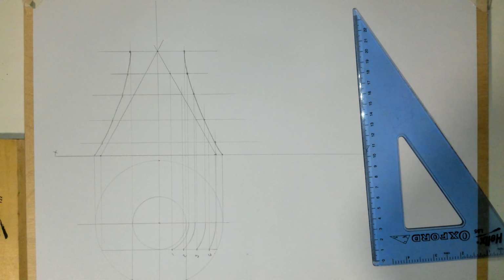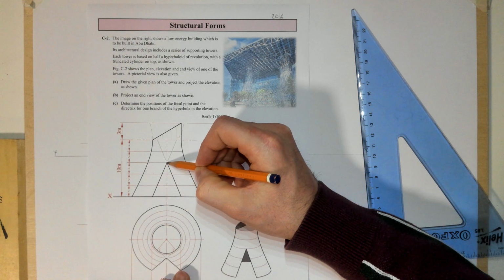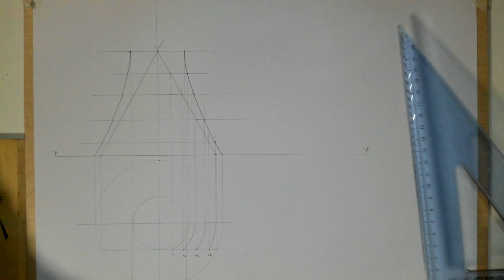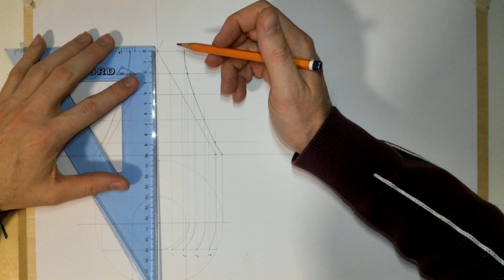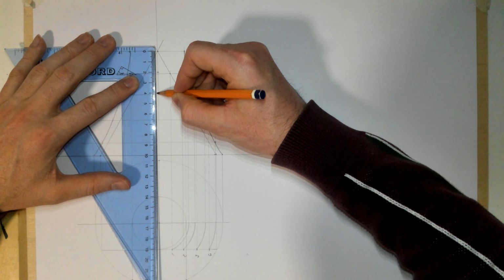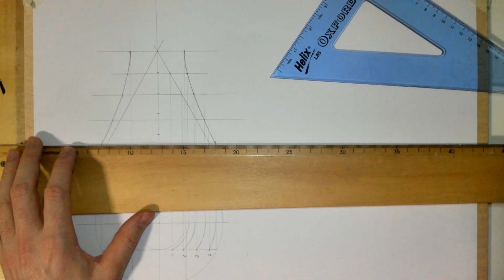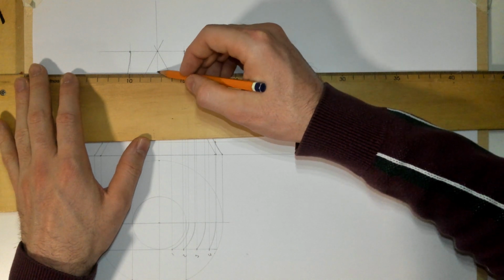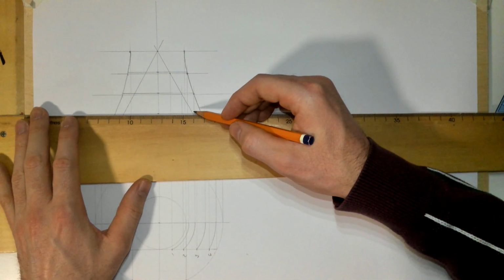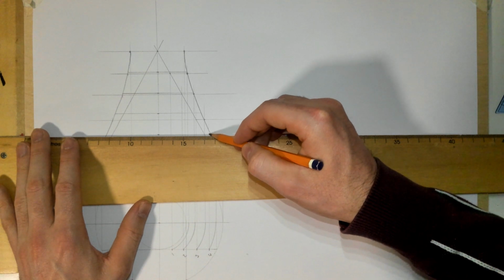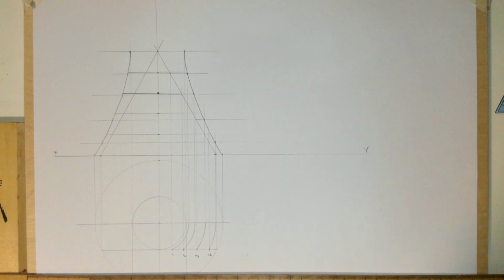And then we're told that this top section is divided up into 5 equal spaces, and that point hits line 3 up there from the bottom. So if we were to divide that into 5 equal spaces, going up to the center point there, the whole thing is 100. So each one would be at 2, 4, 6, and 8. Draw them as lines going across to both sides. Try and don't get them confused with the lines from before. There, and we're told that the V goes up to that point in front elevation.